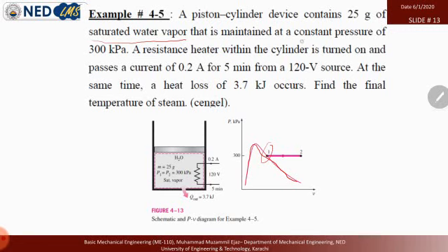Yes, that is maintained at constant pressure. So even after that the graph works like that. On the temperature versus entropy graph, the graph acts like this. So it is a constant pressure line on the TS diagram, but now it is a pressure volume work diagram. At constant pressure, when the heat is applied, the volume will increase. It is telling that it is maintained at constant pressure, so pressure stays constant. That's why it is moving like a straight line from point 1 to 2.